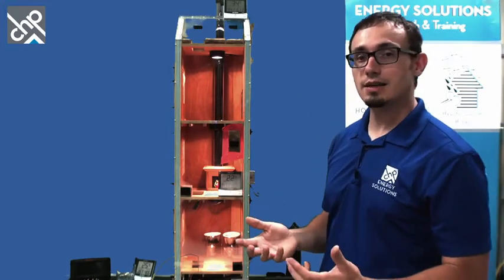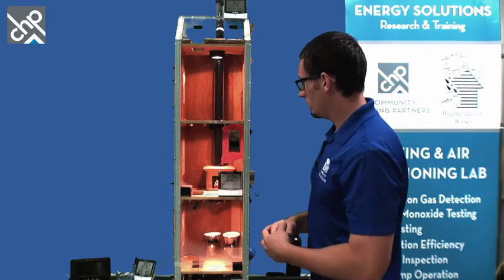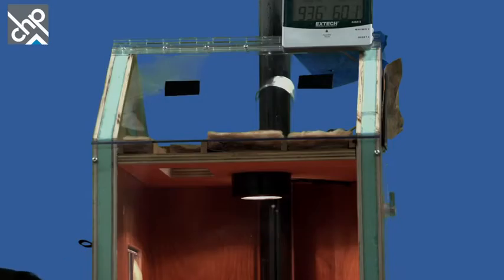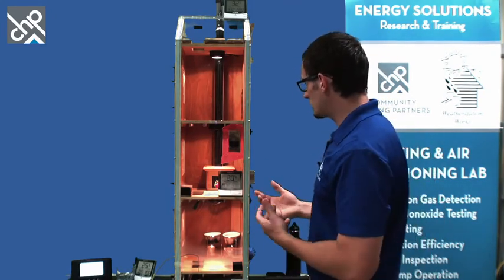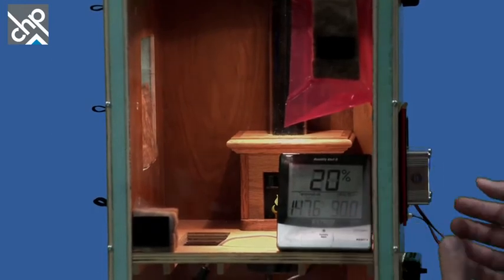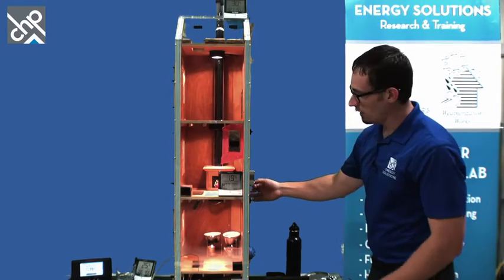Well, what are some of the unintended consequences of ventilation? So we've got a negative pressure in the house. I know that because I've got a fan here. Could measure my pressure inside the house with my manometer. Get that turned back on. So I'm exhausting the air out. I see the relative humidity is dropping and the dew point along with it. So this is a good thing in terms of moving that moisture to a place where it's not going to be an issue anymore. But one of the unintended consequences, you guys know the drill here. So let's go ahead and unplug my exhaust fan.